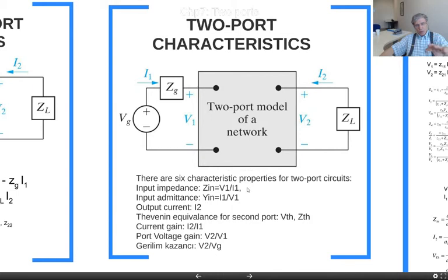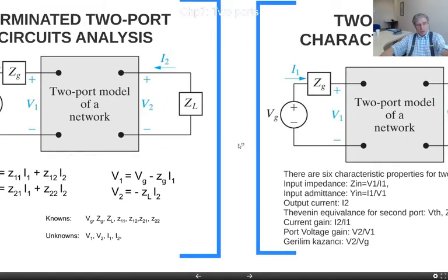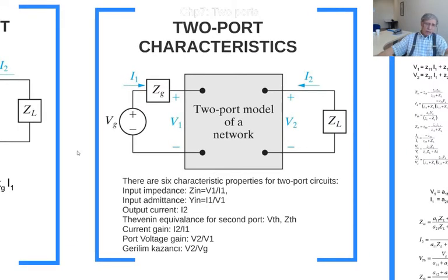So these terms are commonly used in electronics, so we've got to make a relation between the unknowns that we found here and these new characteristics. Some of them are important. Let's mention the gain is important, of course. Voltage gain, current gain, we can easily see that. And this input impedance, why is it important? Let's say you design a circuit and this is your previous circuit and this is going to be the load of this circuit, isn't it?